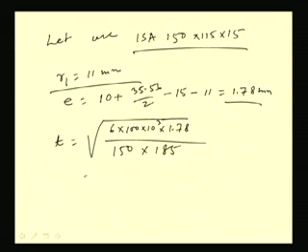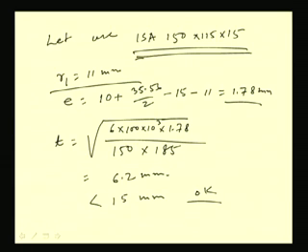From this we are going to find the value of T as 6.2 millimeter, which is less than 15 millimeter. That means it is okay. If we use ISA 150 by 115 by 15, then the angle is sufficient to carry the load. So the dimension of the seat angle is perfectly okay.